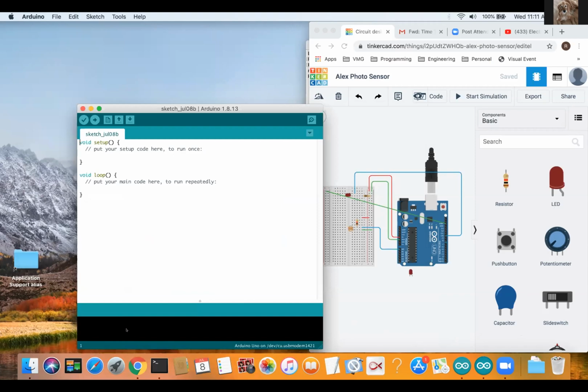Too many windows open. Are we allowed to cut part of the wires off the resistors because they're kind of long and hard to get in the holes? You can cut if you want to. Or you could just bend it slightly differently so that the resistor leg is shorter. Oh, okay. We try to close this one too.